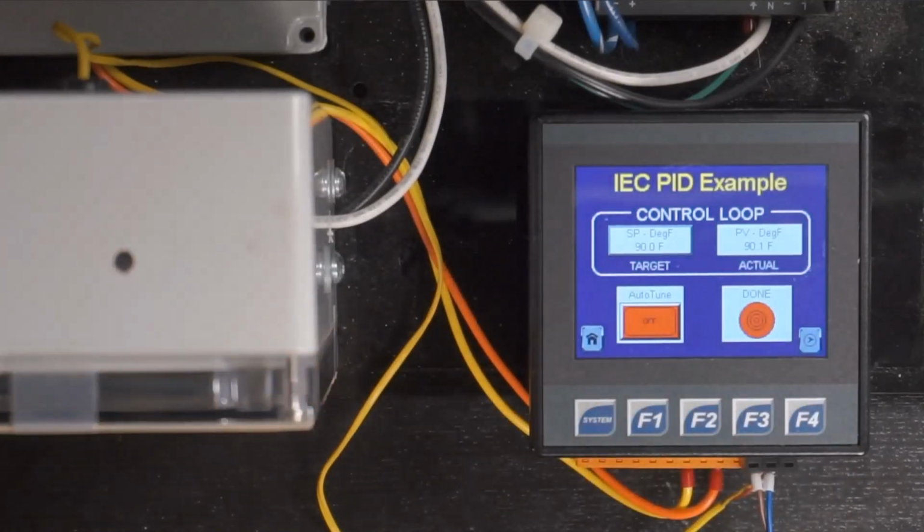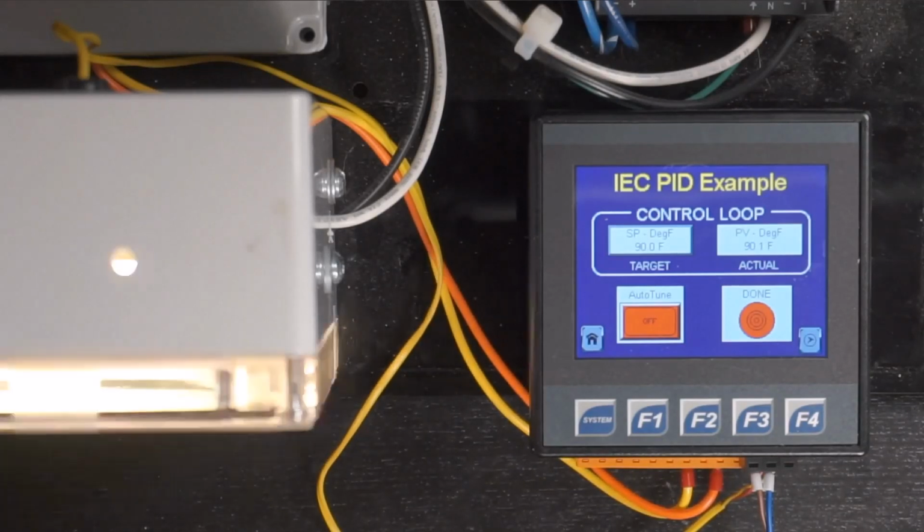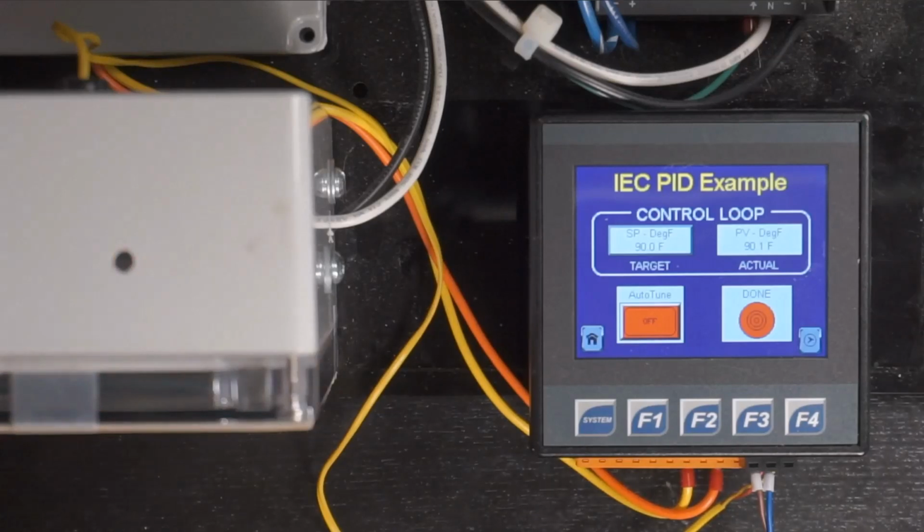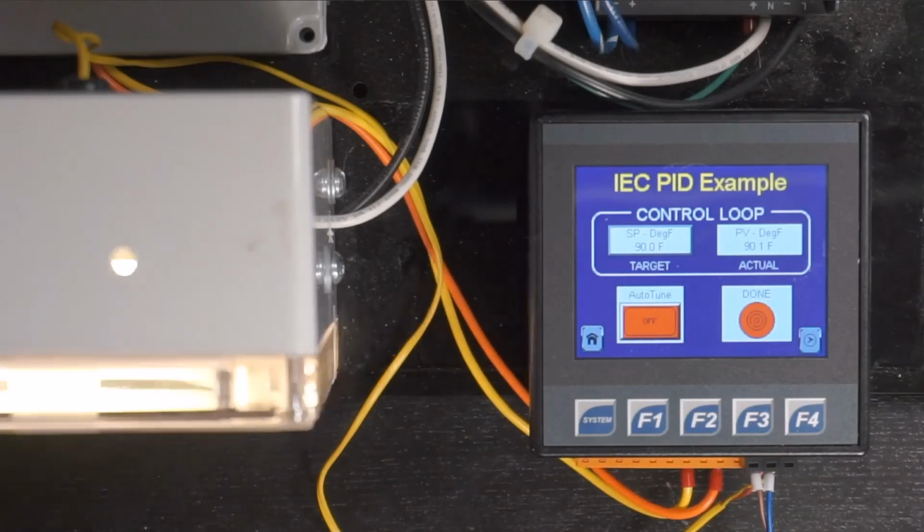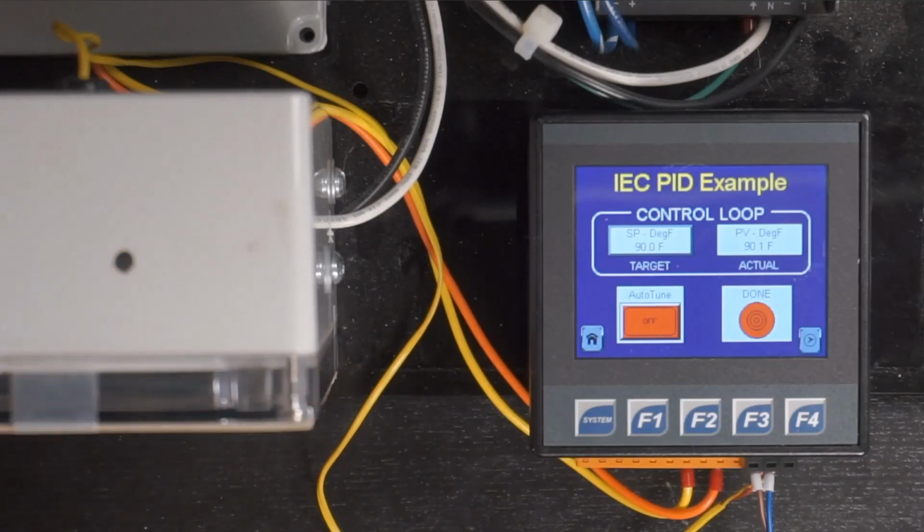Well, I have the auto-tuning screen, which if I turn on the auto-tune button, then we'll dive into that modified Ziegler-Nichols process. We'll run through the process 3 times up and over the set point. And then the OCS itself will write the P, I, and D coefficients that were a result of that experiment into the coefficient terms. So that's how that works. And of course, when it's done with that experiment, the done bit will turn on.